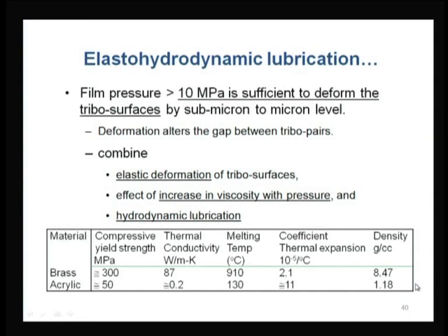So, that is an advantage. There are some factors: the melting point of acrylic is less than 130, that means we should not apply or induce too high an ambient temperature. Another reason to avoid high temperature application is the low thermal conductivity of acrylic material.